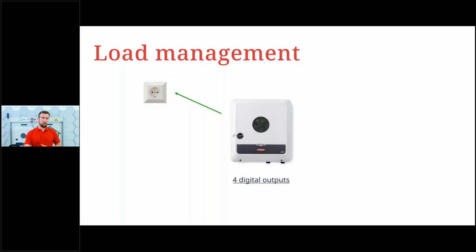That might be, for example, an SG-ready heat pump. SG-ready heat pumps are ideal in combination with a PV system as they already have an input for that 12-volt signal. A heat pump will then switch into state 3 and increase the temperature that it generates by a few degrees, something we don't notice as homeowners or as inhabitants of a building, but something that we will notice when it comes to that energy bill at the end of the month, when we see that we didn't have to use energy from the grid during the night because we generated enough heat during the day.